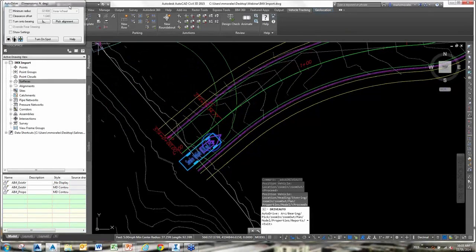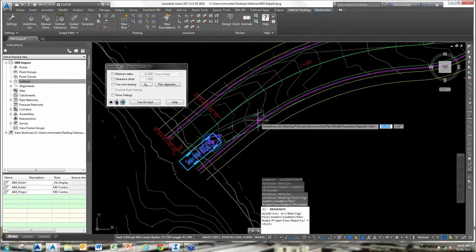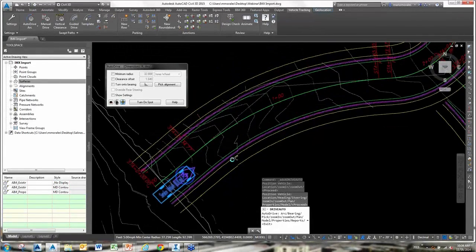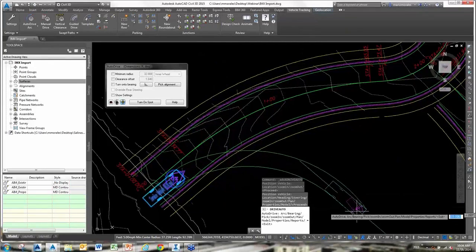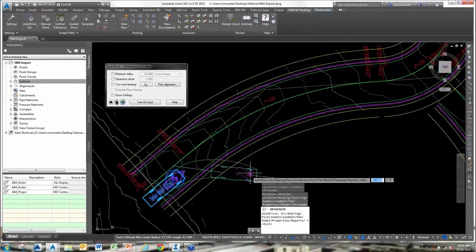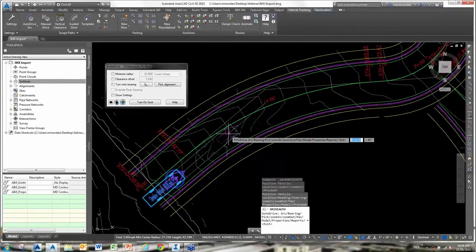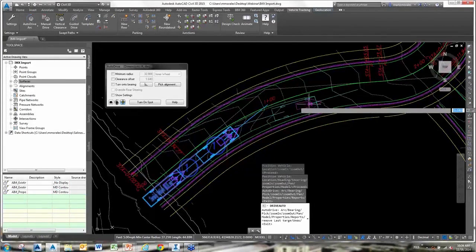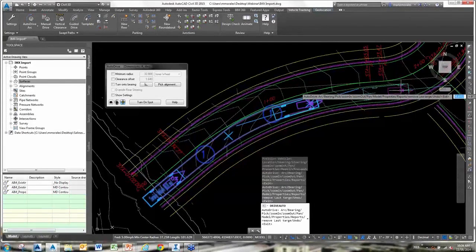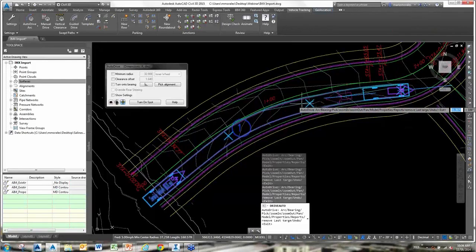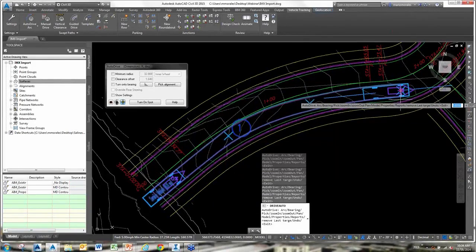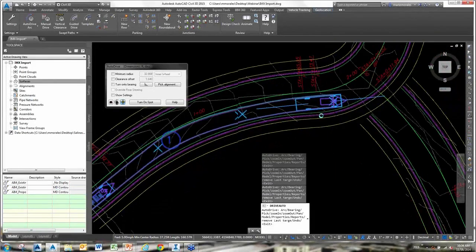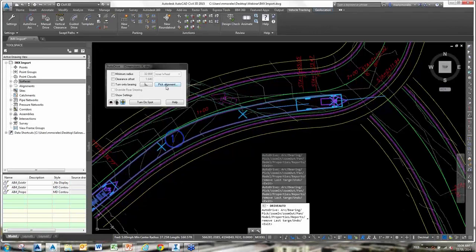So now I have another little dialog box hiding off in the corner. And you can see I've got the vehicle attached to my cursor, and it's showing me the maximum turning radius of this vehicle. So I can just go ahead and click and place. If I oops, I can always just back up and remove spaces, things like that. So no big loss there. I can also choose to move on an alignment, selecting this alignment here.